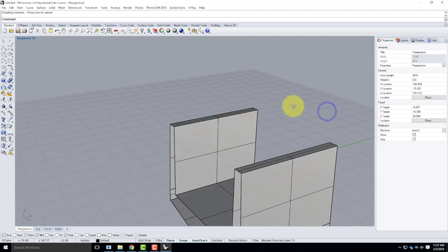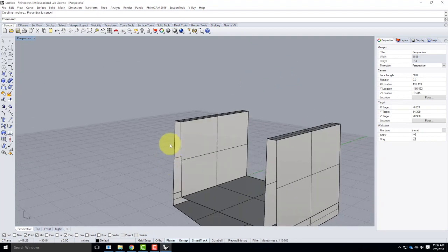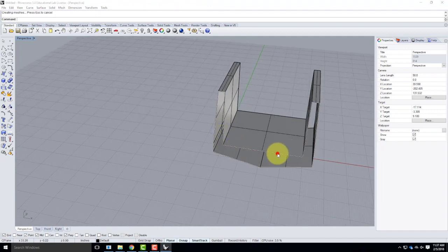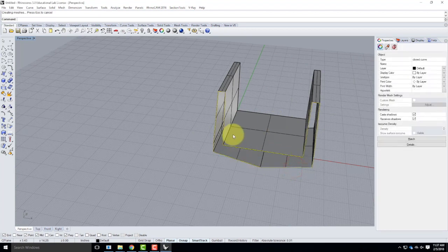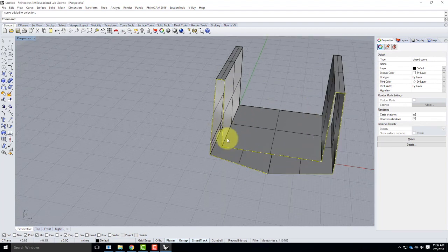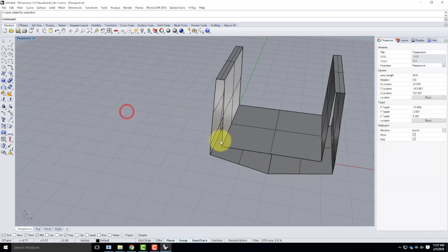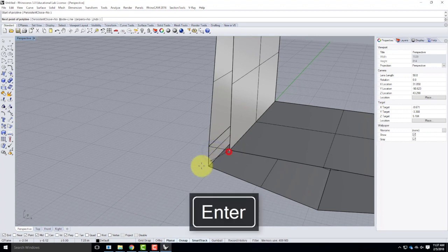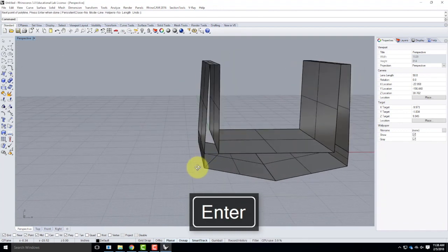So now that I have those surfaces all the way around, I need to create surfaces on the ends. One of the strategies certainly would be to cap this shape or to patch this curve at the end. The problem with those comes later on, and that is we're going to end up causing some bevels and we're going to have trouble. So instead of that, I'm going to make smaller little sections. And you guys saw on the sample, I actually drew little curves in there and there. You don't have to draw those little curves in, but they can be beneficial.